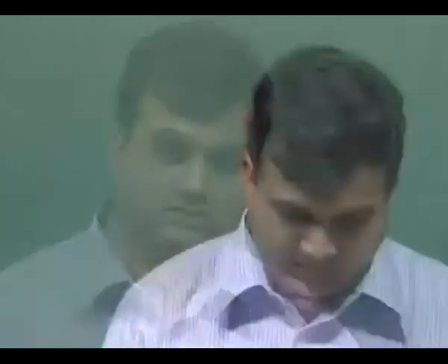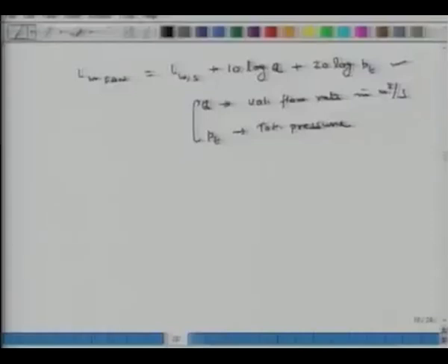So I can use this table as long as I am not computing SPL at the blade frequency. Now to compute the SPL at blade frequency, the last column you have is called BFI, blade frequency index. So you add that blade frequency index number, that is also in decibels. So this is the overall approach.